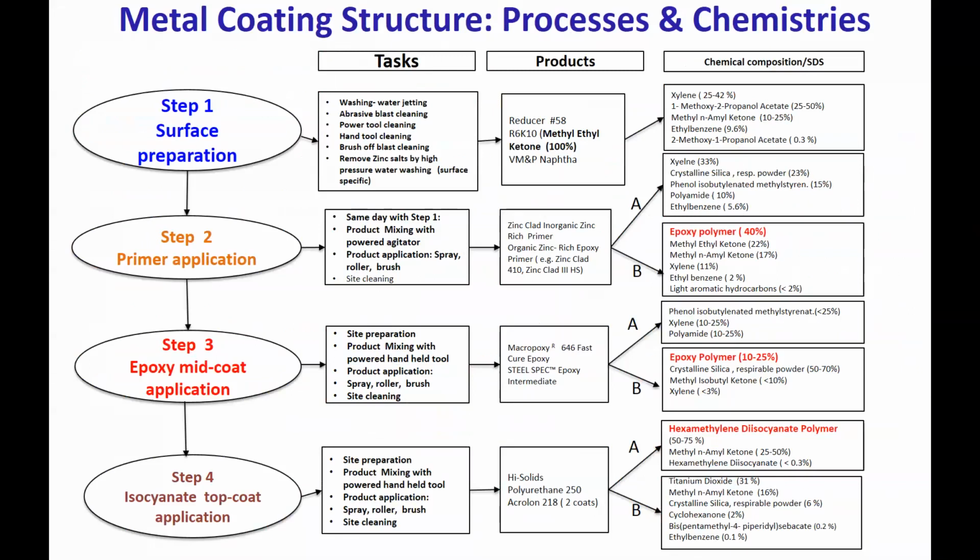Sometimes we have seen in step 2 isocyanate-based mid coats, which are sometimes based on polymeric methylene diphenyl diisocyanate, or polymeric MDI. And other additives, we have also seen polymeric TDI in a few cases, and paratoluene sulfonyl isocyanate, which is used as a sort of scavenger of moisture in these containers and to improve their shelf life. Top coats are aliphatic isocyanates that are quite similar in chemistry and performance to the motor vehicle repair industry.